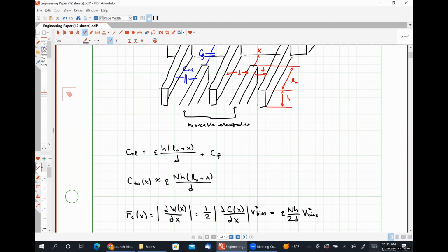Okay. This is actually a good thing because it means we don't have to worry about pull-in or anything like that. The larger the voltage that we apply, the larger the force that we get, and for a particular mechanical suspension spring constant Km, the larger the displacement that we get. We don't have to worry about plates snapping together or anything counterbalancing things. We simply have a force that's acting to increase the capacitance.